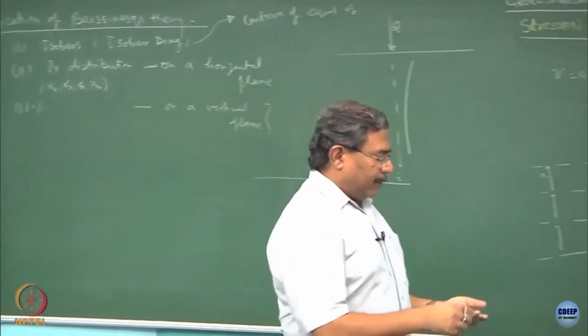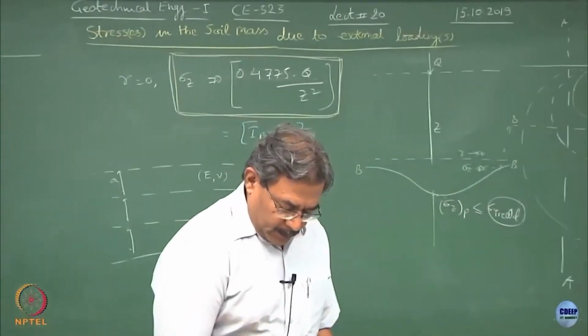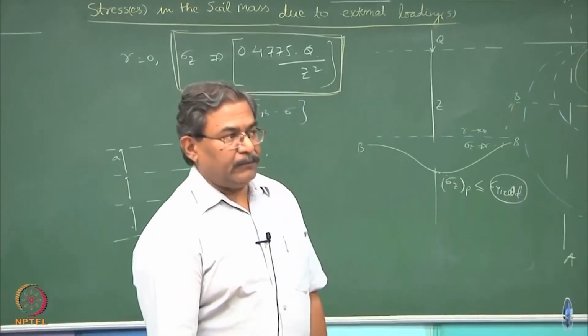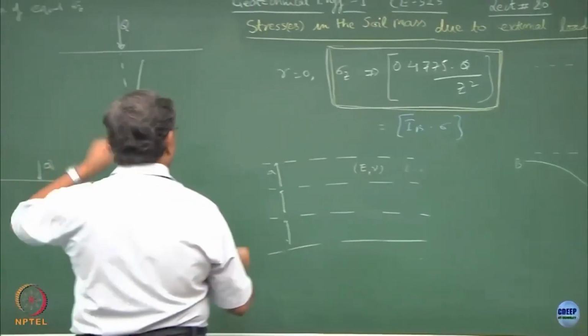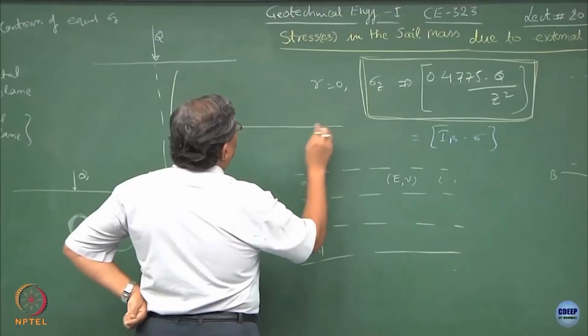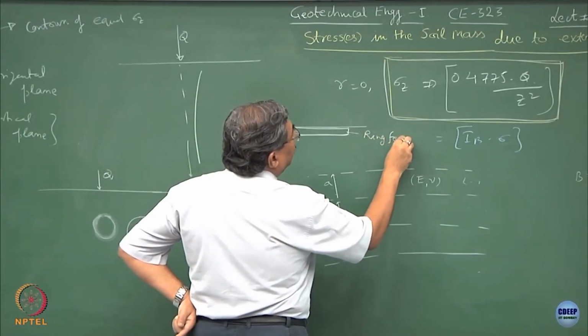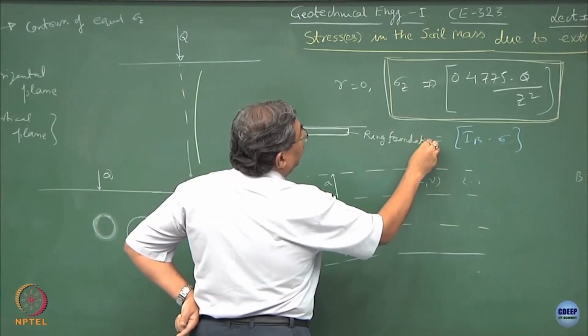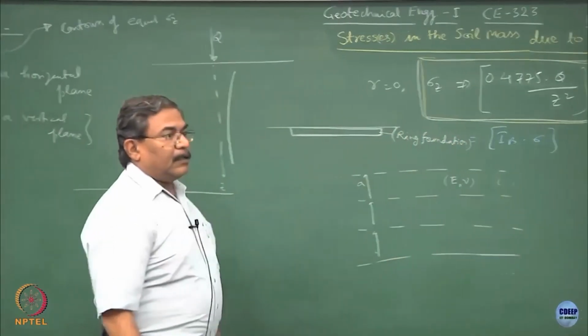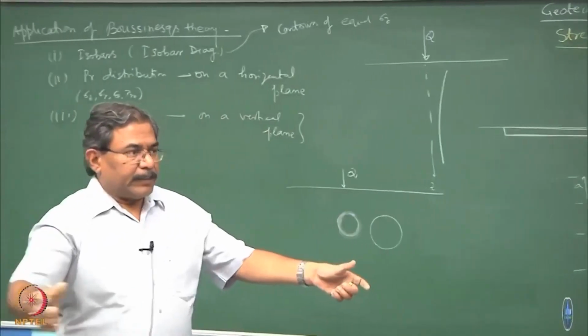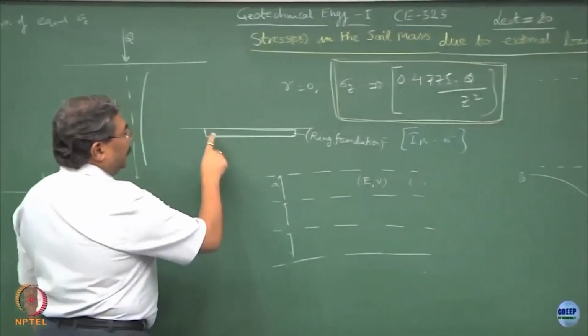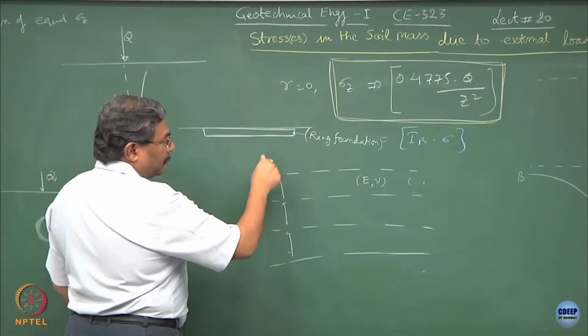But suppose I am designing a tank foundation, which you must be seeing, big tank farms in your structure. So, this becomes a ring foundation. Normally the oil tanks are seated on a ring foundation. I need not spend so much money because rafts are going to be expensive.